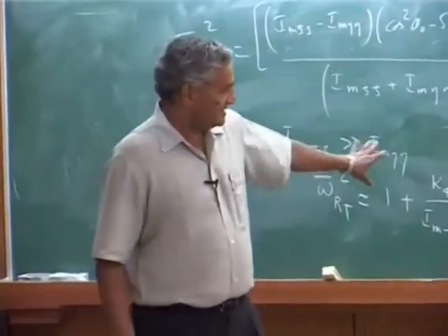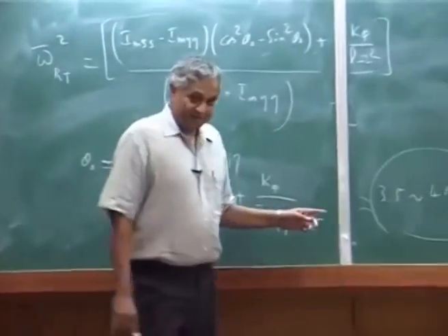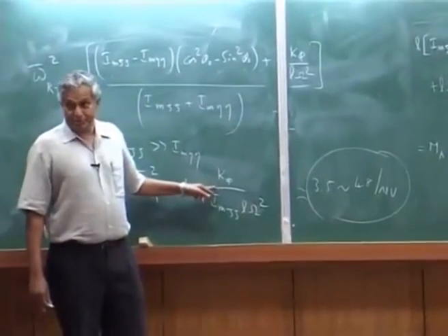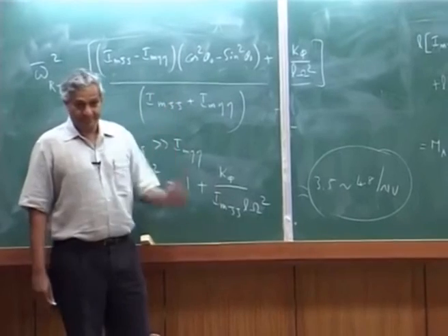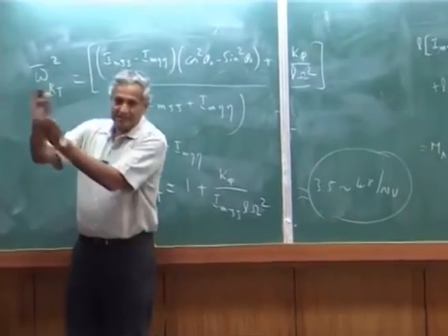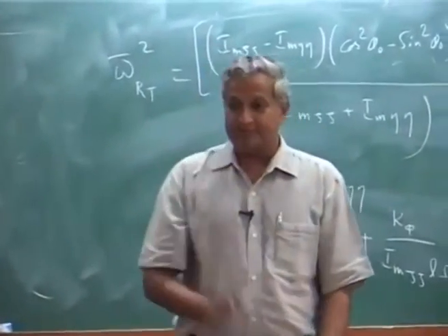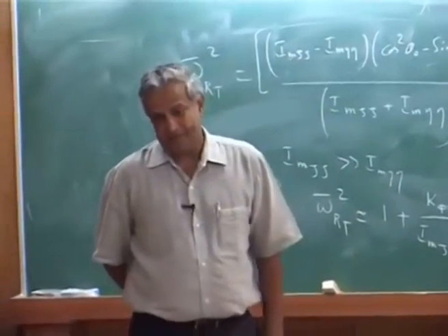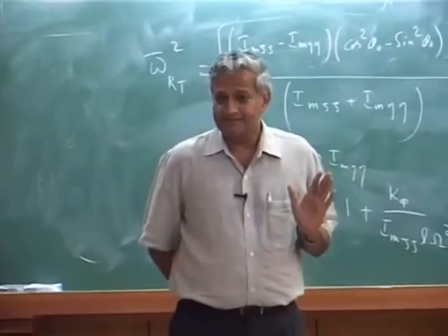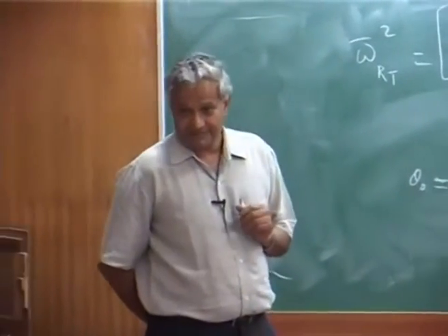Because you don't want to bring this and have a problem. This is mainly dominated to a large extent by the control system. Okay. So if you want to analyze the blade dynamics, you need to know the control system stiffness. So that has to be calculated separately by stress analysis, because you have to get some estimate of the torsion stiffness.